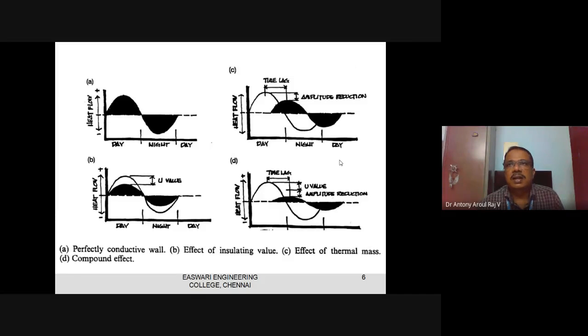In a summer condition, or in the equatorial region, or in the tropic zone, these things will be happening. That is why in the load calculation, it is transient. Transient means whatever we have outside will not be there inside, but there will be a drop in the temperature and there will be a shift. In other words, heat value will be reduced, and the maximum will appear after 4 o'clock or 8 o'clock, depending on the thickness of the wall. So that we have to understand.